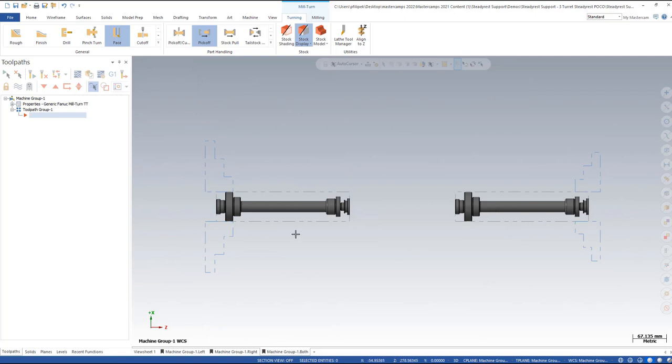And we got our setup done here, so we got our jaws there. We're going to come and pick off here, pull that back, and then we'll do a facing op on the end on our right spindle.